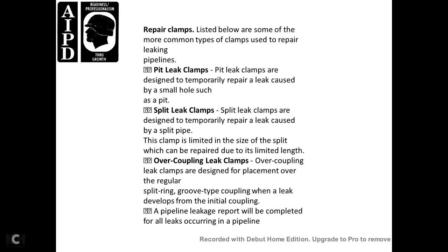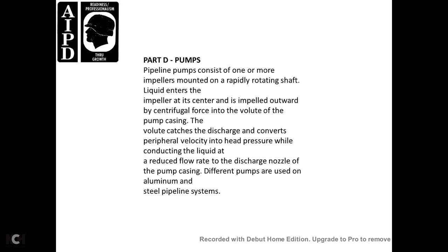Overcoupling leak clamps. Overcoupling leak clamps are designed to be placed over the regular split ring of the groove type coupling when a leak develops with the initial coupling. A pipeline leakage report will be completed for all leaks occurring in the pipeline.